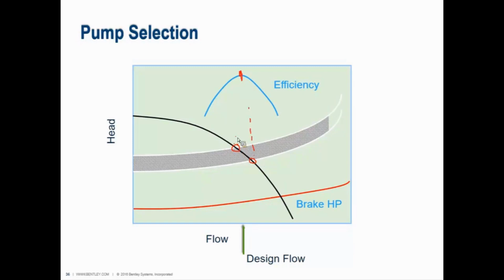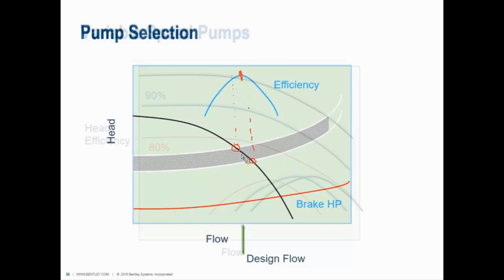If it doesn't match up well with the maximum water level on the tank, then maybe you might need to pick a slightly different pump or change out the impeller a little bit. That way you're optimizing the pump and being as efficient as possible. And that's how you would probably answer that design, is just changing out the pump curve a little bit because you have a different pump impeller, and see how well that works.